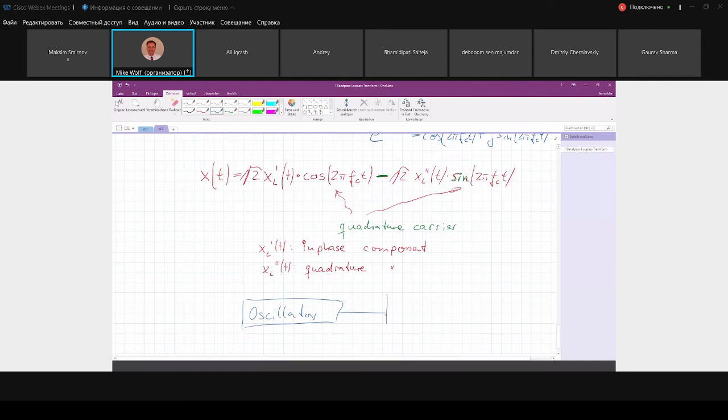Then you split this up and make a time shift of t naught. The time shift is just 1/4 Tp, or 1/(4 F naught). The period of this carrier is Tp, which is 1 over F naught. If I introduce a delay which is a quarter of a period, a cosine becomes a minus sine. This is the whole story.